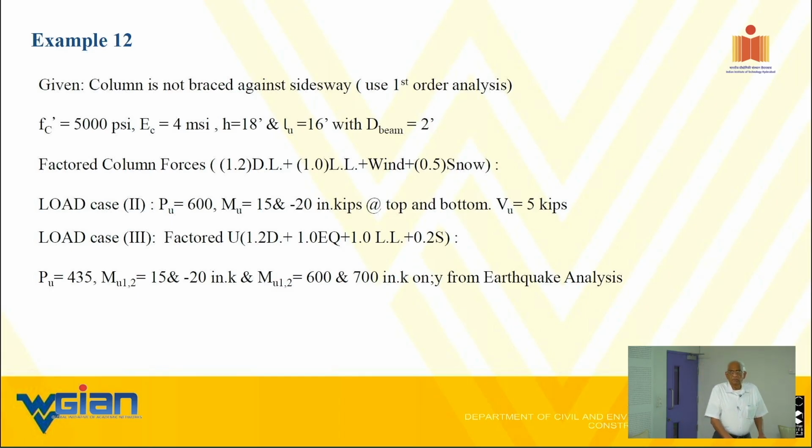If you remember, I said most of the load factors are above 1. But here, when you get into the combination, it is that 1.5. Why? Because in combination with wind, snow is not going to be 100%. In combination with wind. That is the key word.